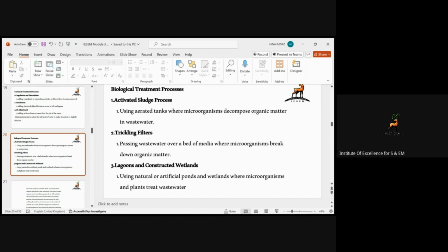Here I want to mention that you can't cultivate vegetables or fruit in this phytoremediation technique. You have to be very clear about it, because the toxic metal would re-enter the food chain. So you have to pick a suitable species.